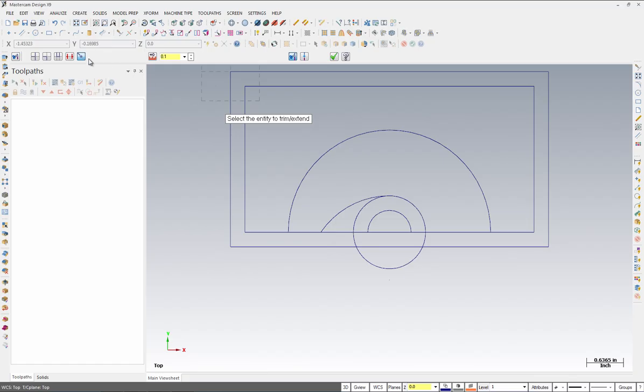From this point, we are going to select Trim to Entities. We are going to select here and trim to here. Again, your geometry should look as shown. Change to the divide function up at the top. From here, we are going to delete this center line. Select OK when this is done.